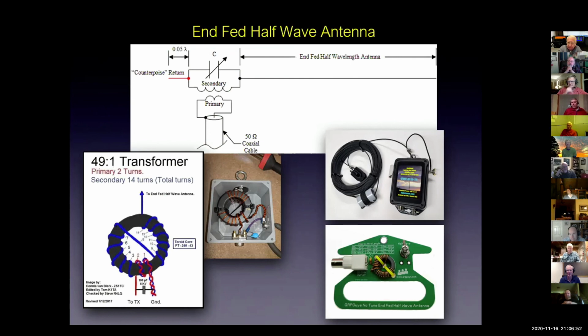I've heard a lot of the same things that everybody's saying, and it really underscores what Chip said: a resonant dipole is a much more efficient radiator. The issue with the dipole is that it's center fed, so you need to support the center. You're going to have a big sag, so for portable operations it's not as ideal. The other problem is it's tuned to a single frequency or an even harmonic of that frequency. If you want other frequencies, you need to do a linked dipole or a fan dipole or a little more complicated antenna.